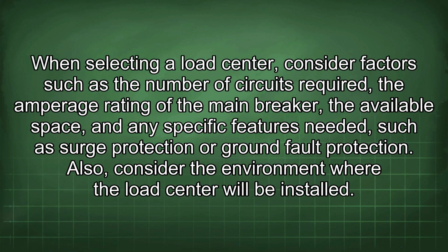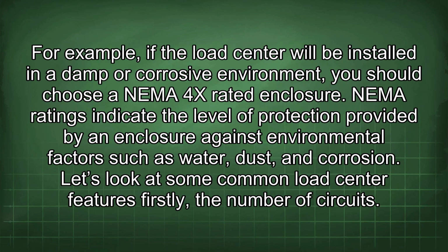When selecting a load center, consider factors such as the number of circuits required, the amperage rating of the main breaker, the available space, and any specific features needed, such as surge protection or ground fault protection. Also, consider the environment where the load center will be installed. For example, if the load center will be installed in a damp or corrosive environment, you should choose a NEMA 4X rated enclosure. NEMA ratings indicate the level of protection provided by an enclosure against environmental factors such as water, dust, and corrosion. Let's look at some common load center features.